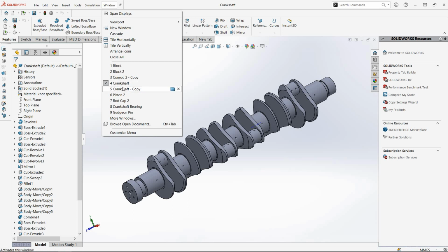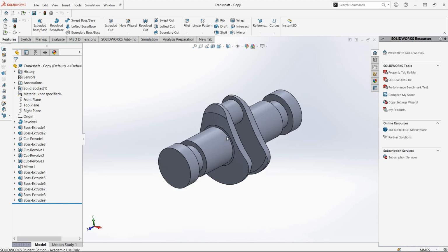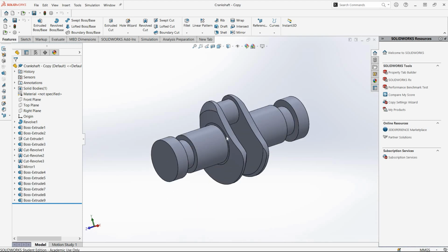Moving on, though, to the actual crankshaft that I ended up designing. This essentially is the same crankshaft you saw before, just modified so it can fit the V-twin design. Now I will note too, one thing I did have to modify, because the guy in the YouTube video did not account for this, is clearance. So I ended up having to shrink these joints right here. These are not exactly to spec of the video, but for the sake of clearance and the ability to rotate the damn thing, I just redesigned that.